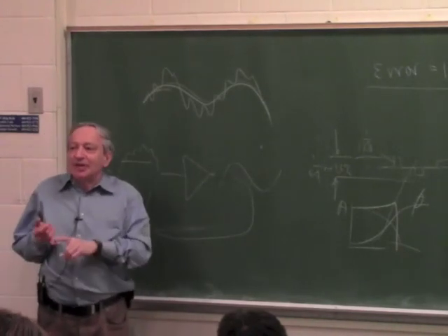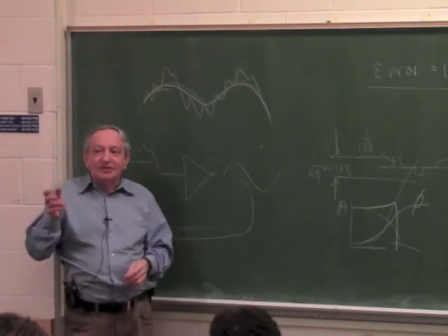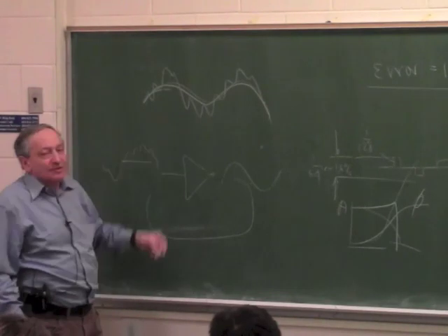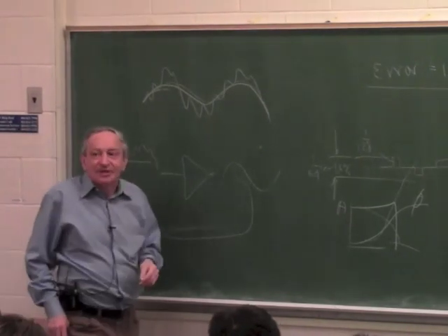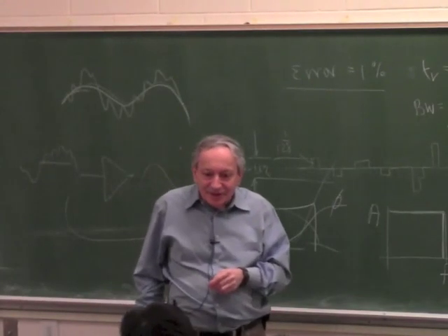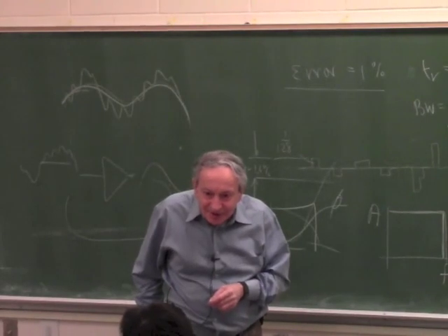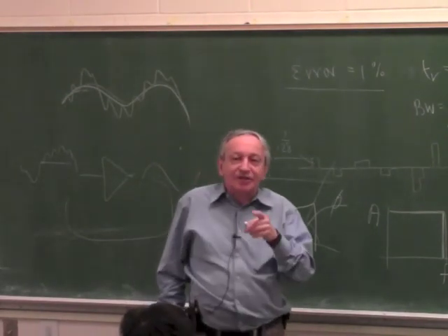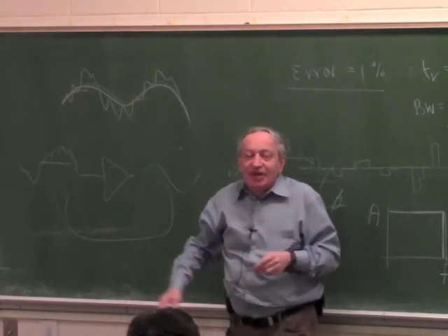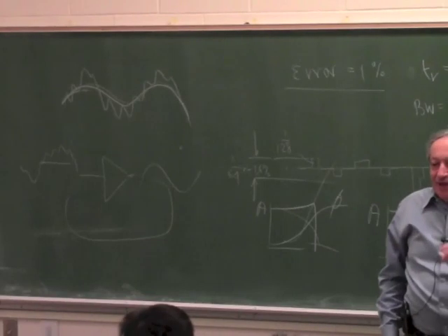So reason number one, aliasing. Okay, if it goes to a digital system. But even if it doesn't go to a digital system, there are two important reasons why you want a filter. You don't want this noise to get into the system. Yes. Because a signal with a new frequency will be generated. Okay, so the answer is a new frequency can be generated from these two frequencies. And how can a new frequency be generated? Because of nonlinearity. Very good.